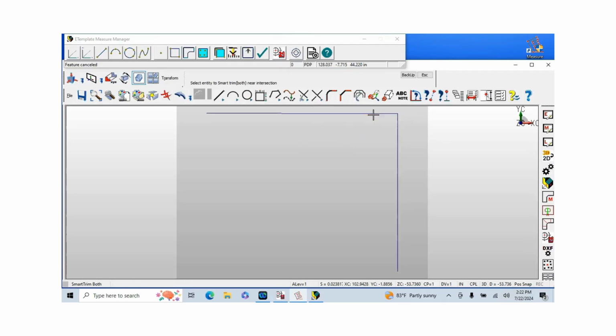So we'll use the Create Corner tool. And now, as I start to go into the cabinet layout process, this angle here is not 90 degrees. So what I want to do is a make square function. We're going to keep this as my reference and let this wall line move. Select that, and now it's a true 90 degrees.